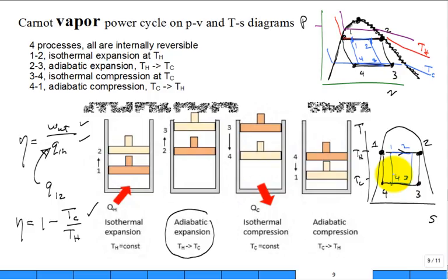They will, because all the heat is brought in at the same temperature, TH, all the heat thrown out at TC, and every process is internally reversible. Yep. Pardon? Is that a corollary? Yep. One of those corollaries where they say that once you have everything maximally efficient, then regardless of how you might change it, use air as a working fluid, steam as a working fluid, refrigerant working fluid, go from saturated liquid to saturated vapor in the boiler, or 20% to 80% in the boiler, it always is going to have the same efficiency. It's almost too good to be true. It's a startling result. That such a simple equation can have such a profound, widespread application.